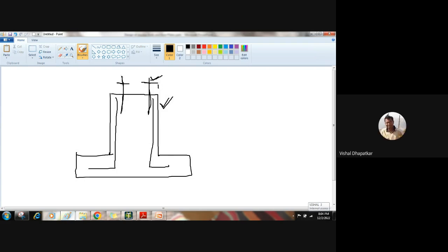Correct. So ductile failure is always preferred because, first thing, the bolt will not fail suddenly. Before failing, it will absorb a lot of energy whenever there is a seismic event or wind. Before failure, what will happen? It will try to elongate, right? As it elongates, it will show you the deflection of the structure, but it will not fail the structure immediately, right? In the column or in the beam, you can find some displacement or deflection or some odd shape because of elongation of these bolts.